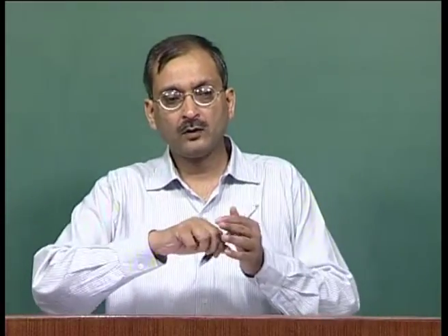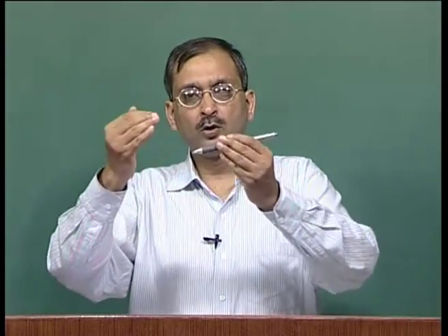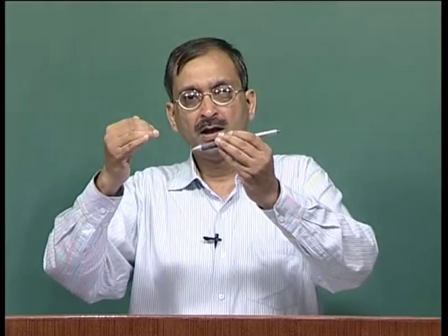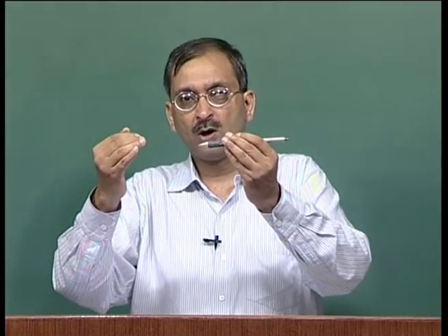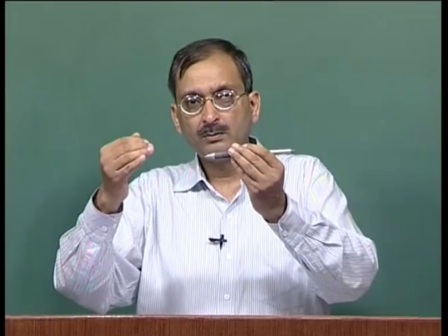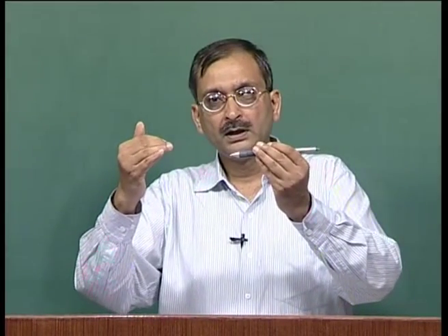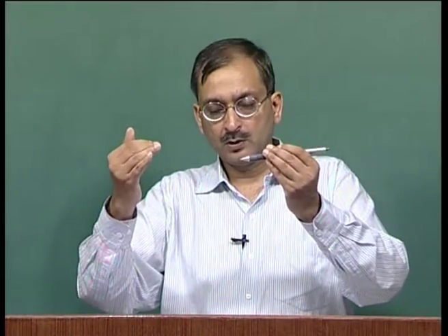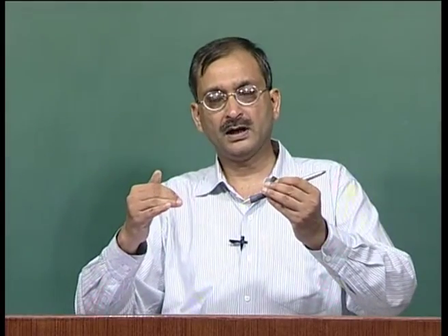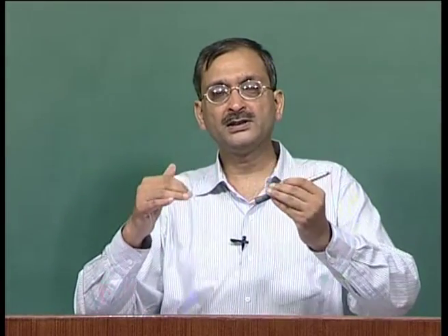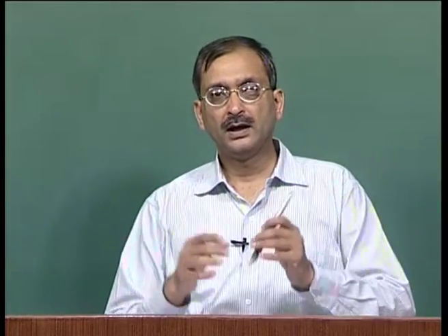So, what happens to the cone of depression? Initially, when things were unsteady, the groundwater table was horizontal, and the cone of depression starts to form. Initially, its size is very small. As the pumping is continued, the volume of this cone of depression keeps on increasing. After some time, with prolonged pumping, it reaches a constant volume or a constant state. This is called the equilibrium state or equilibrium condition. At that point of time, both S and H become constant.